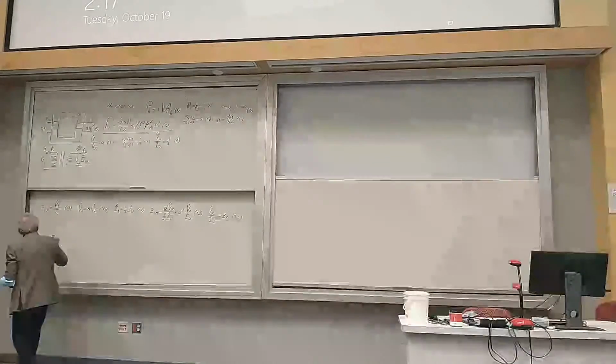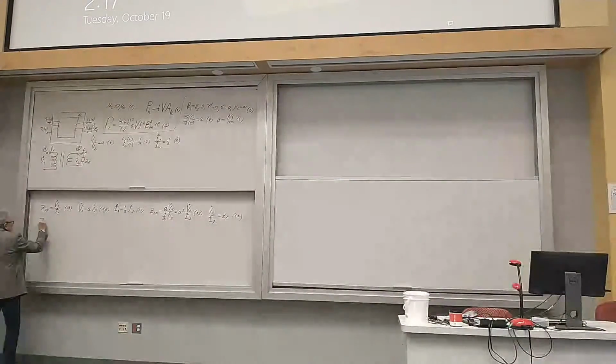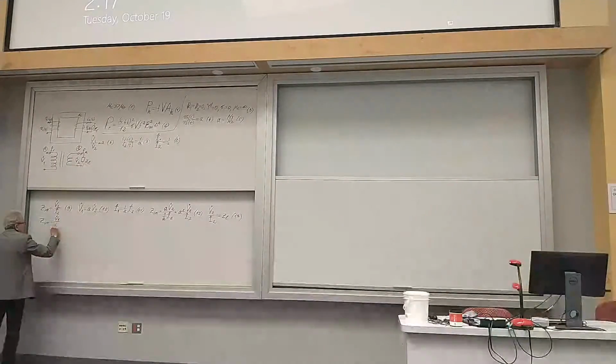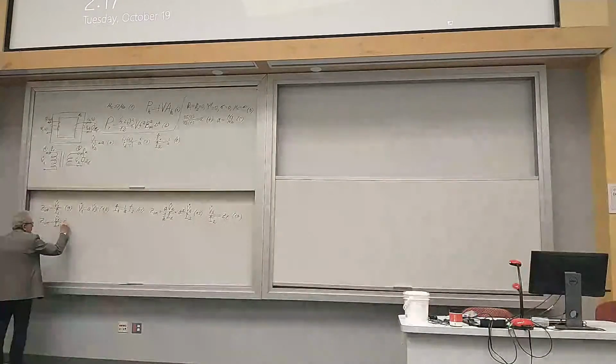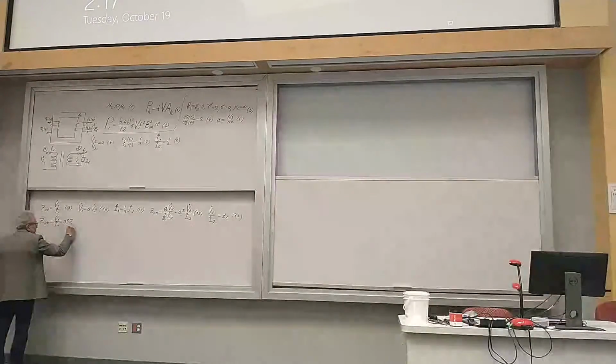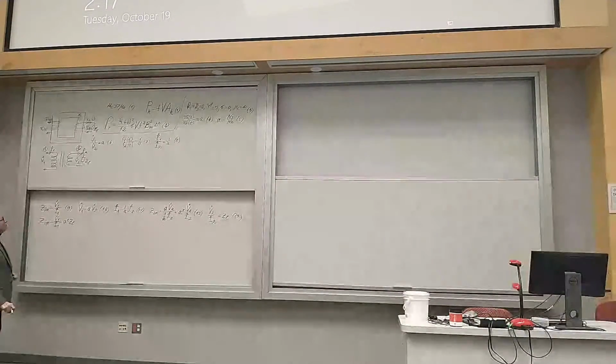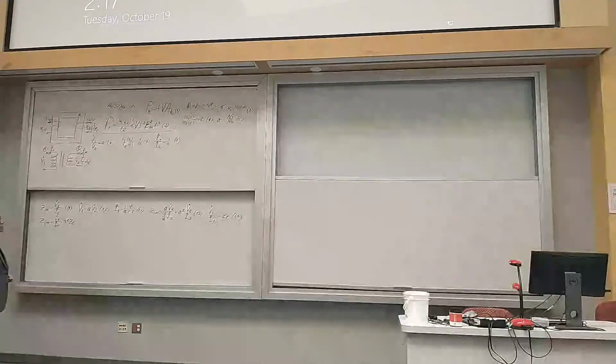Consequently, we will find this expression for the input impedance, which is equal V sub 1 over I sub 1 is equal to A squared times load impedance, where A is a turn ratio. It's defined by formula 5.